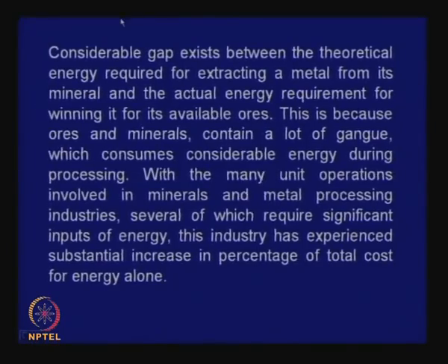So, you get the idea that we have to spend energy in the initial steps before we come to decomposition. And this is what I said, that a considerable gap exists between the theoretical energy required for extracting a metal from its mineral and the actual energy required for winning it from its available ores. This is because ores and minerals contain a lot of gangue, which consumes considerable energy during processing.